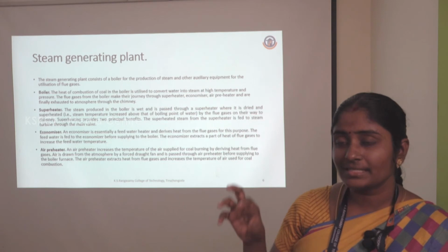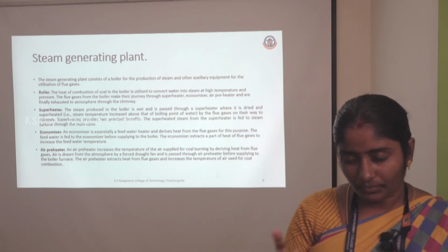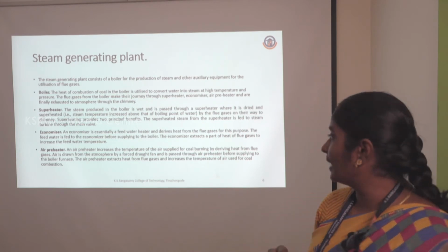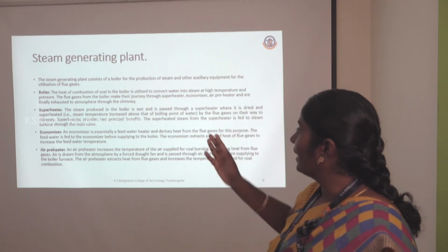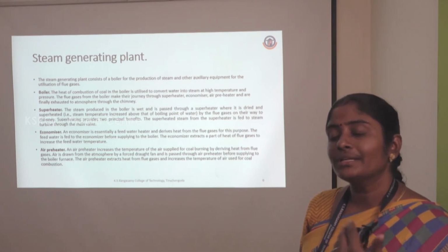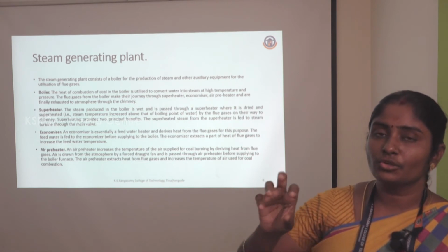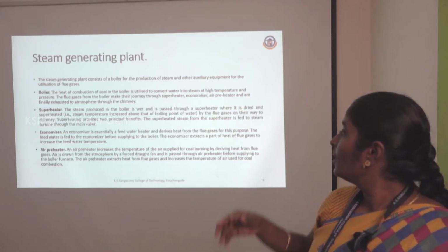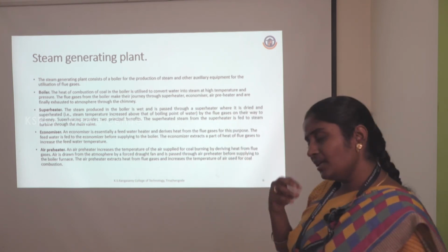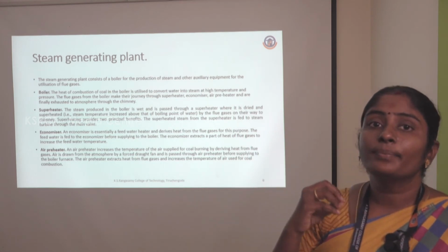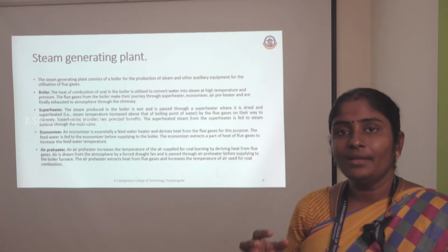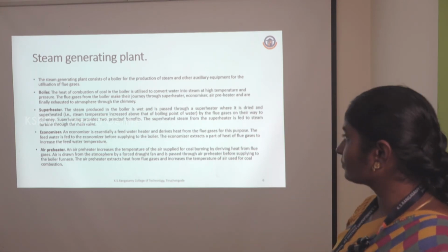Because of the increased pressure in the steam, it runs the steam turbine at a proper level. After the superheater comes the economizer. The process of the economizer is to heat the water before it enters the boiler. When it enters the boiler, the water is already heated because of the presence of the economizer. The air preheater is also like the economizer; the coal is injected with the preheated air, which reduces the time to burn the coal.